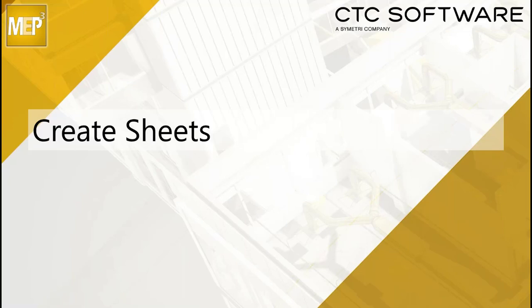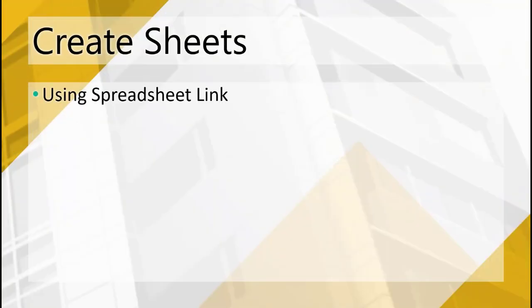Here, we need to create sheets for all these construction document views. Not all my views, just my construction document views. And so we're gonna go through and create sheets. Now, what I like to use for this is Spreadsheet Link.